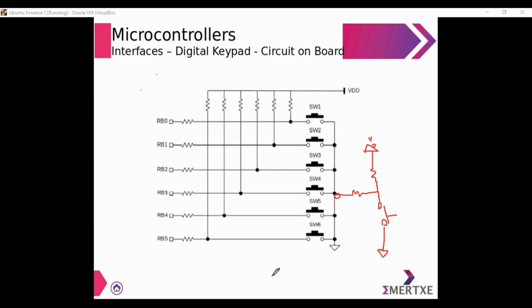Okay. So we are going to concentrate on only pull-up circuits, because on our board what we have is a pull-up circuit, but you should be able to program a pull-down circuit also, because right now you have the basics of how a pull-down circuit works. In our case, because it is pull-up, we are going to concentrate on the pull-up circuit only.